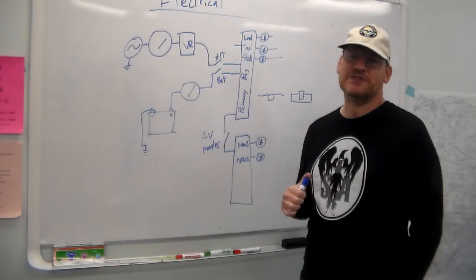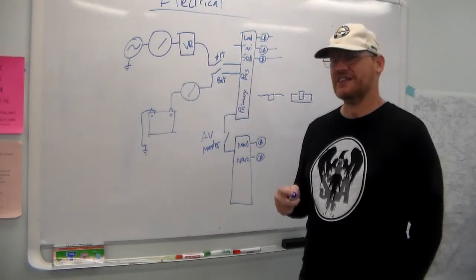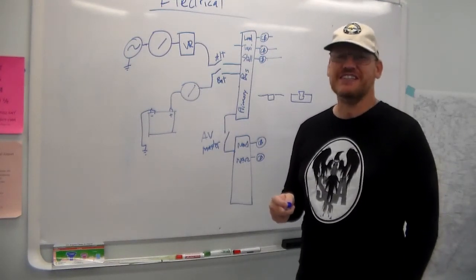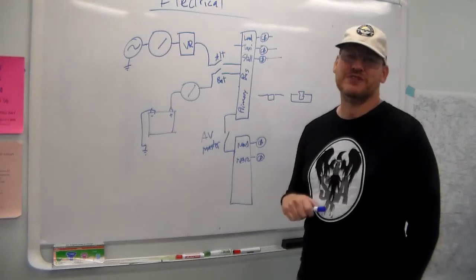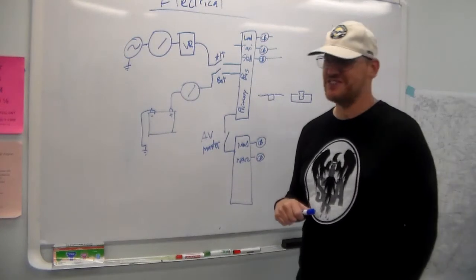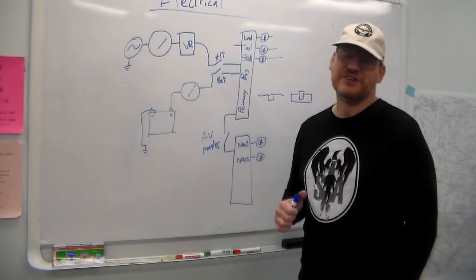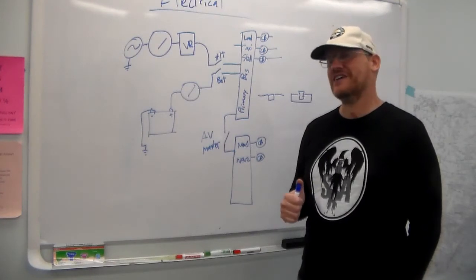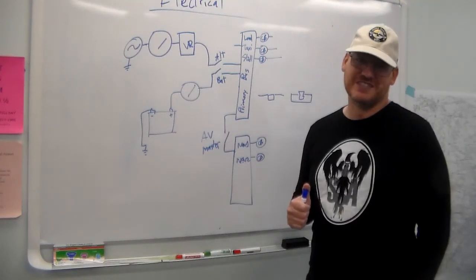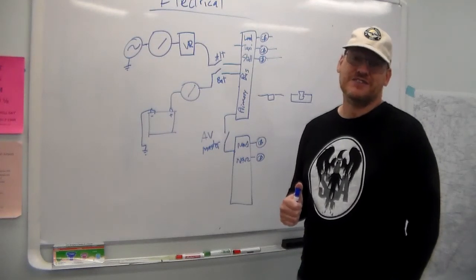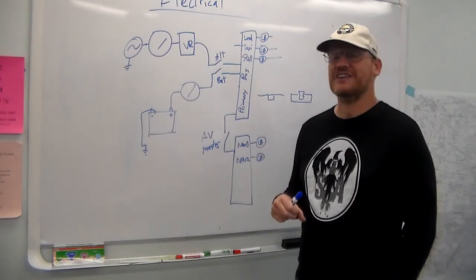Well, he was flying with his girlfriend. His girlfriend had taken some pictures, and in those pictures you could clearly see that that alternator field switch was down. So in other words, he didn't follow his checklists, and in that particular aircraft you had about an hour. If you ran everything, you had about an hour's worth of electricity to drive everything before everything would start to go offline.